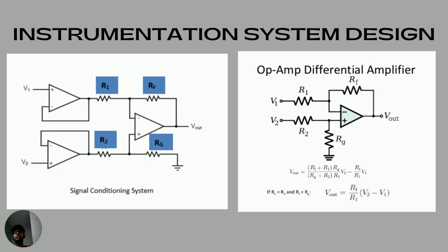So in this case, the gain designed by me to build a measuring scale uses an RF of 220 kilo ohm and an R1 of 1 kilo ohm, which when we divide or calculate it, will give us a gain of 220.